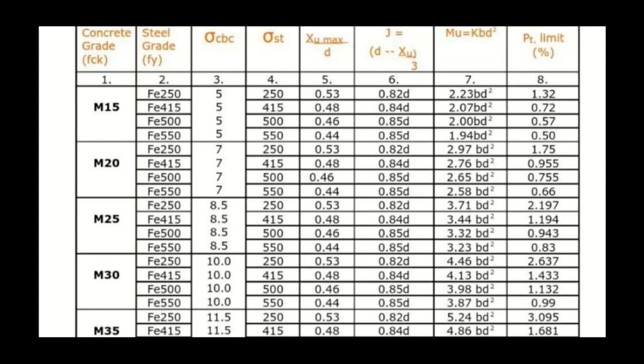If you calculate the value with the formula which I have shown you, or you can find that formula from IS 456 2000 Annex G. If you calculate the values from the formula, you will get exactly this value. So this table has been made depending upon that value, that equation of Annex G.